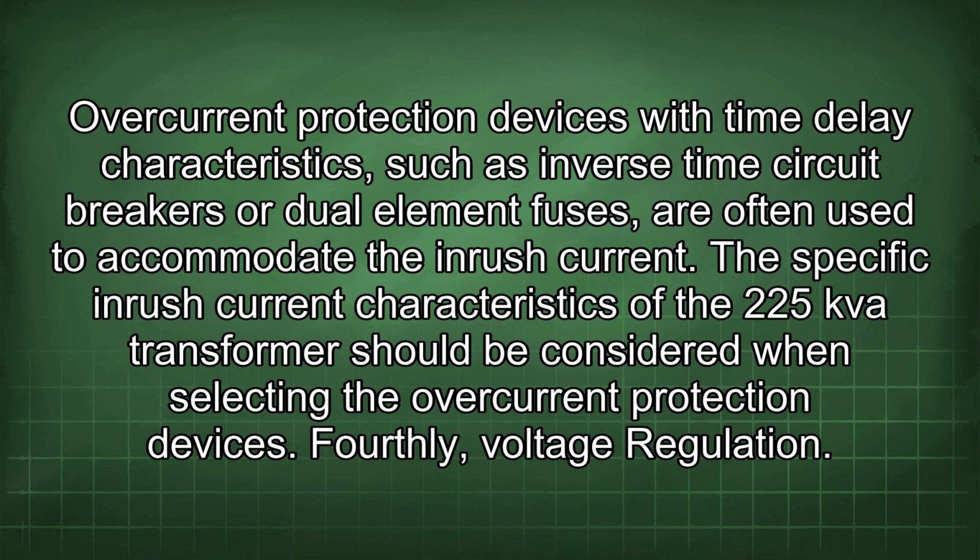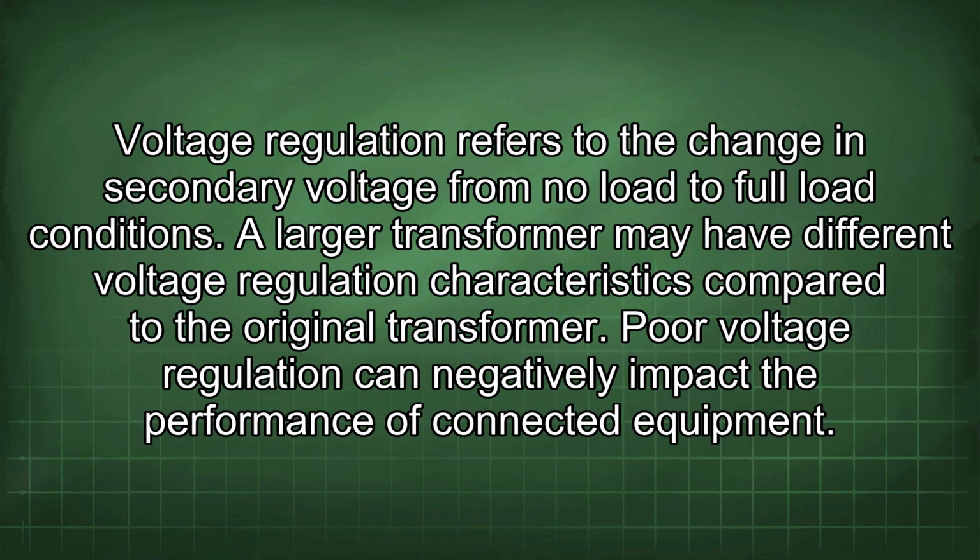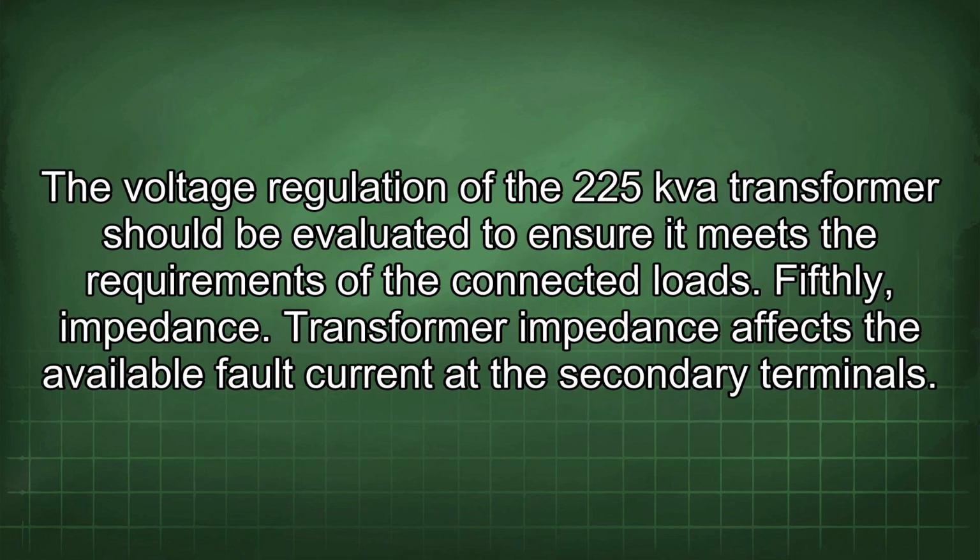Fourthly, voltage regulation. Voltage regulation refers to the change in secondary voltage from no load to full load conditions. A larger transformer may have different voltage regulation characteristics compared to the original transformer. Poor voltage regulation can negatively impact the performance of connected equipment. The voltage regulation of the 225 kVA transformer should be evaluated to ensure it meets the requirements of the connected